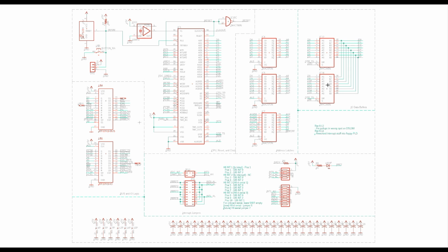So what I did is I stuck 2 transceivers on here, and assuming that we only do an 8-bit I/O port address, when the low byte is asked for, we will take D0 through D7, and we will put this on this ID0 through D7. And that is what I'm calling the I/O data bus. And on the other hand, when the high is enabled, we'll take the upper byte and we'll put it on those lines. And these are bidirectional, so it can go either way. So that's how we take the 16-bit data bus, turn it into an 8-bit I/O bus.